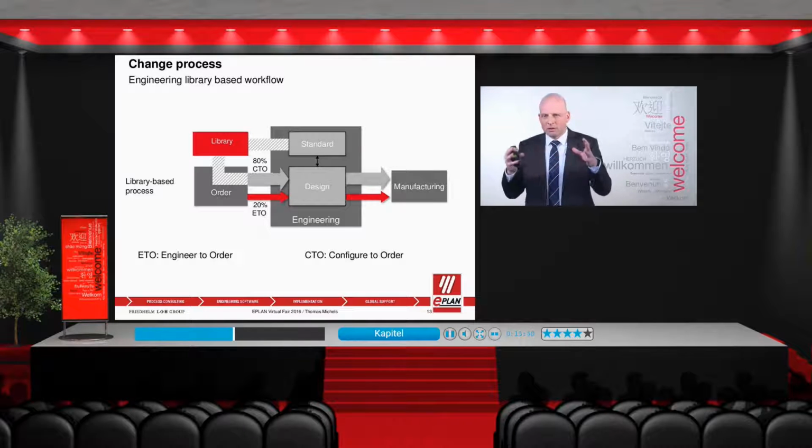So just think about reviewing your existing projects you did in the past. Find out there are parts in your project you can reuse. As I already said, for example, for a power supply or for a feeding unit or for a handling unit or a control unit in your machine or your plant. You take these parts of the projects, maybe a set of schematics, electric or fluid, you take them to the library, and there you do the management inside the library, no longer in the project, you really move it to a library. And then maybe even you have some administrator that is responsible for that library.